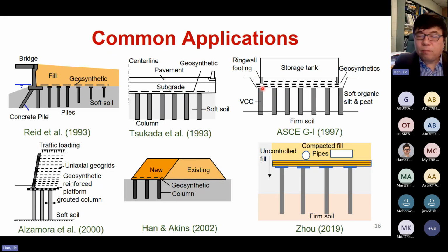They used fiber concrete columns with a 3-layer biaxial geogrid to support the storage tank. I did this project in Brazil, where we used jet grout columns to support a retaining wall with the LTP. I did another project with roadway widening.